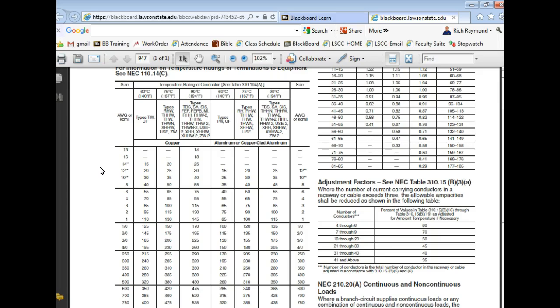15 amps. If we get it in any of these type of ratings right here, then we could rate it at 20 amps. If we come over here and use any of these type of insulator jackets right here, then we could actually run what? 25 amps through that. Now notice all of these are below the 32 amp rating of a 14 gauge wire in 20 degrees centigrade in free air. And this is what electricians use to decide what service they're trying to run, what conductor they're trying to use.